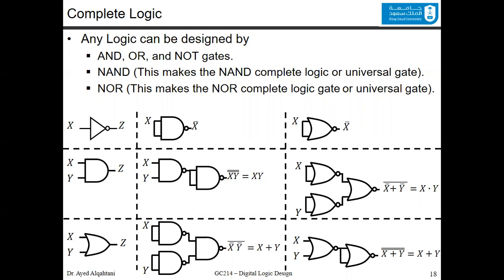We will take advantage of this, and we will say that if you have a 2-input AND, for example, then it could also be represented by converting the AND to OR and inverting both the inputs and the output. Similarly here, for the OR, you will say that it's equivalent to an AND where you are inverting everything, the inputs and also the output.